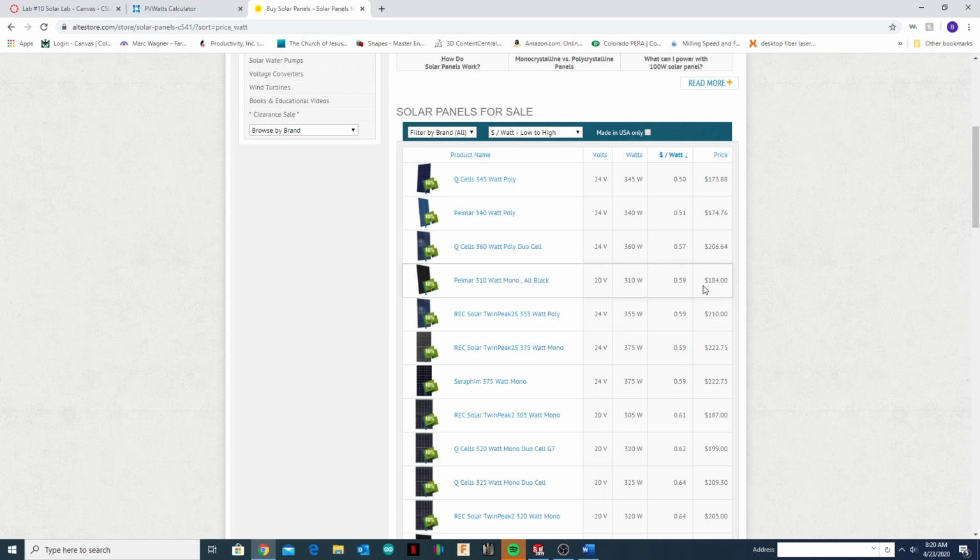Okay. Then for facing west, we needed a 9 kW system. So 9,000 watts divided by 345 would be 26.086 panels. Again, we're always rounding up, so 27 panels. Okay, so that's where you're going to come up with the number of panels. Okay, does that make sense?